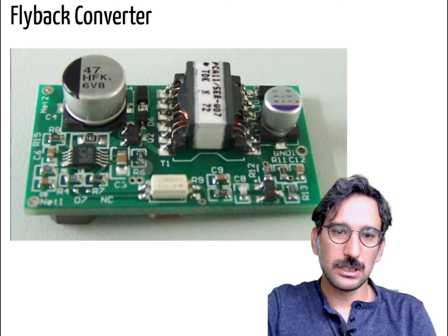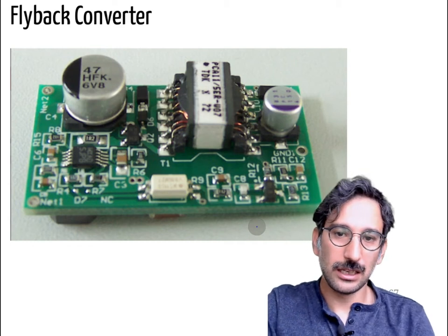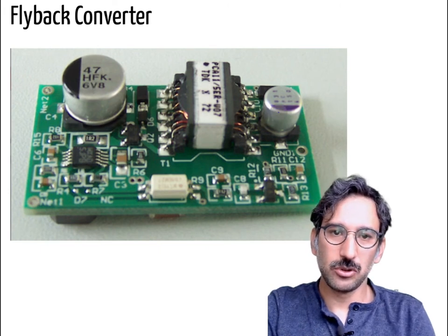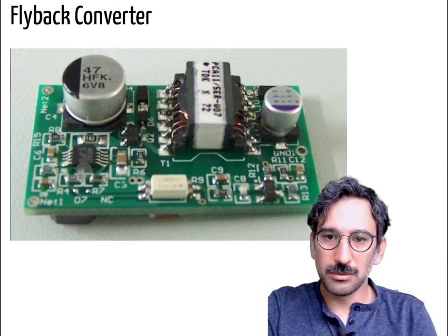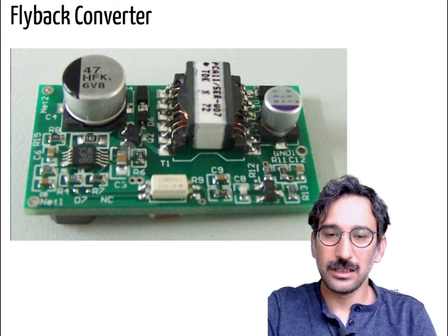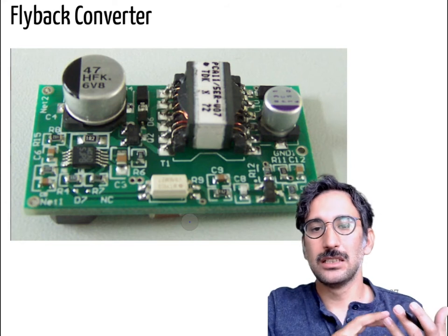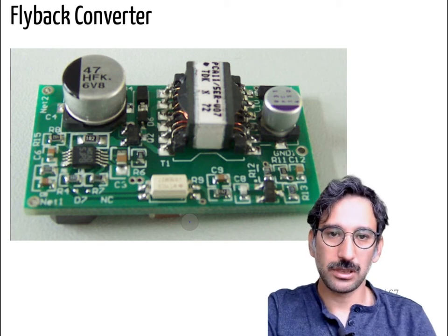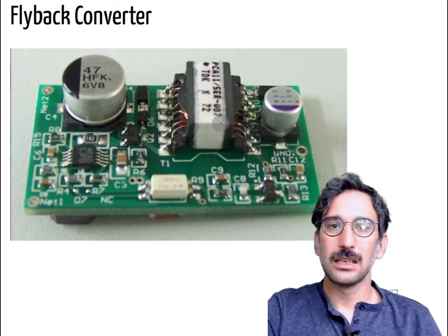Here you see an evaluation board, a sample design. I think you will be able to understand which component is what. You can see the capacitors at the input and output. Probably there's a diode here, and that is probably the controller. Q2 is probably the switch, and it has 3 legs, either a MOSFET or a similar device. Again, we have switches and capacitors, but there are no conventional inductors like a toroid or air core inductor. Instead, we have this kind of component, which is probably a transformer.